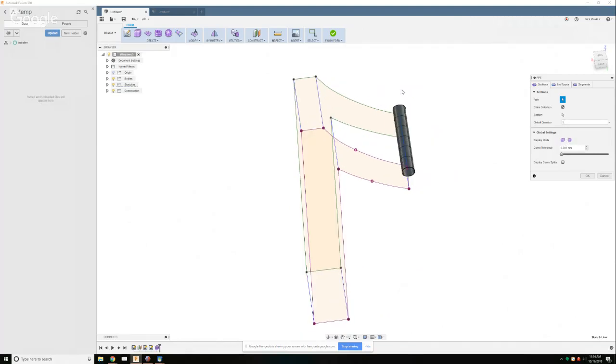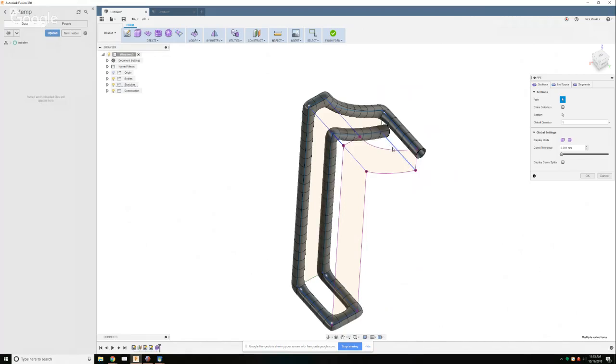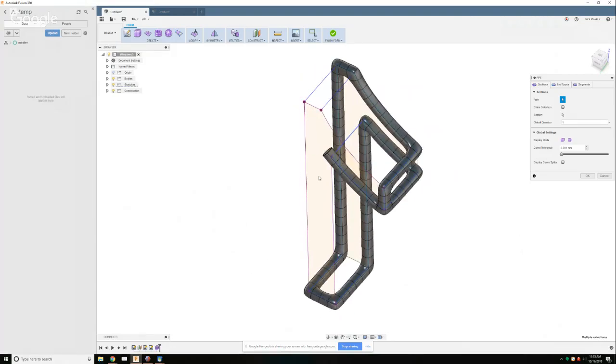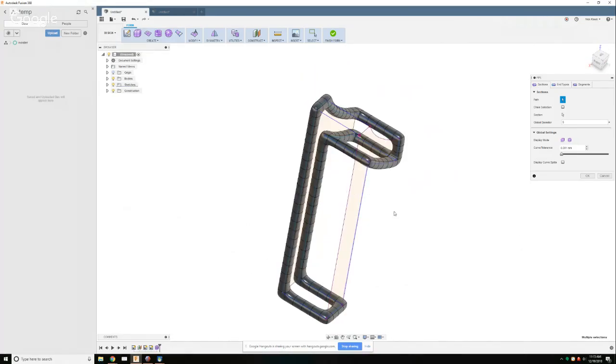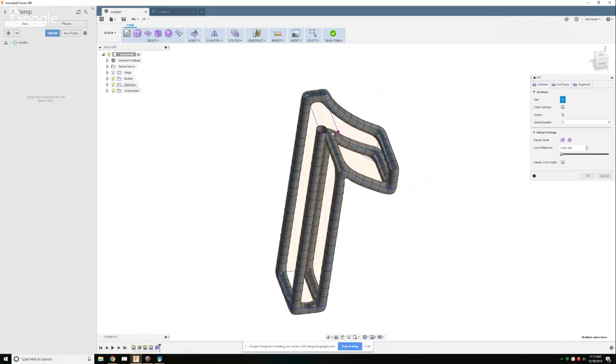So that's one path, but now look, as I click on these other, I'm not even going to chain it. As I click on these other chains, you can see that the pipe is actually adding in to each other. And I click on all of these, the pipe kind of follows down. But I can click also on essentially every single part of every single line inside of here. As you click on it, Fusion will figure out how to connect all of these together.